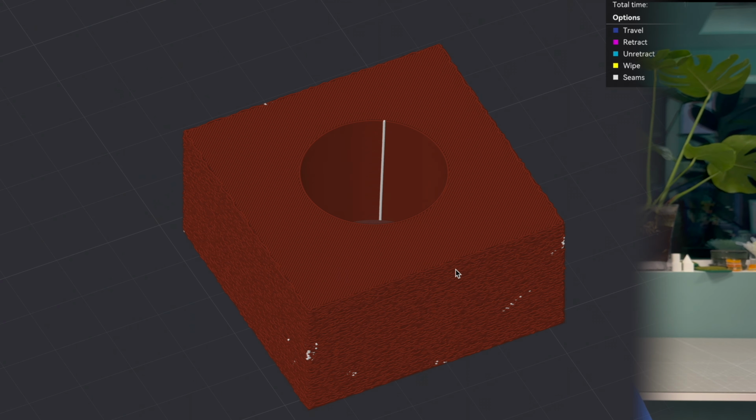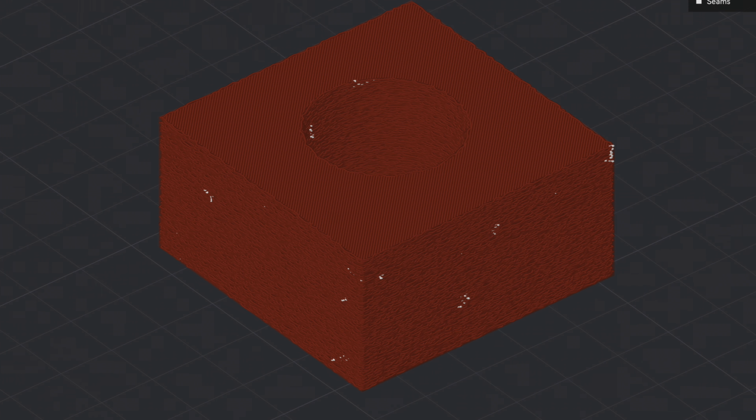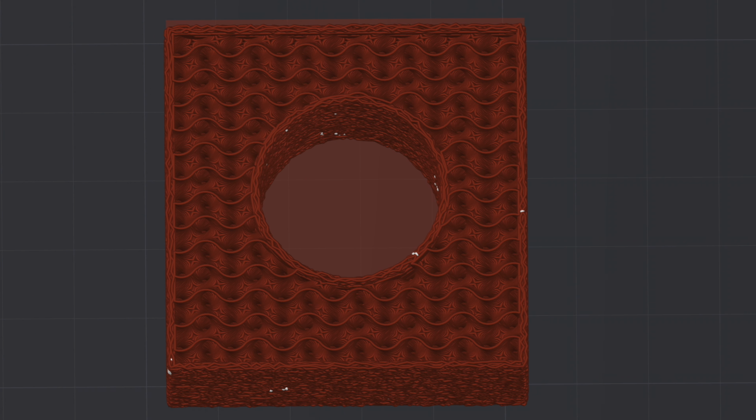It may seem weird that there's an option for both None and Disabled, but the key is in the Allow Paint parenthetical. Disabled means no fuzzy skin ever, while None allows you to paint on fuzzy skin, which we'll discuss more later. The Contour setting only does the outermost wall of the object. The Contour and Hole setting does the outer walls and any holes in the model. Finally, All Walls does every single wall, not just the outer wall, though it's prone to cause collisions and in my opinion is best avoided.